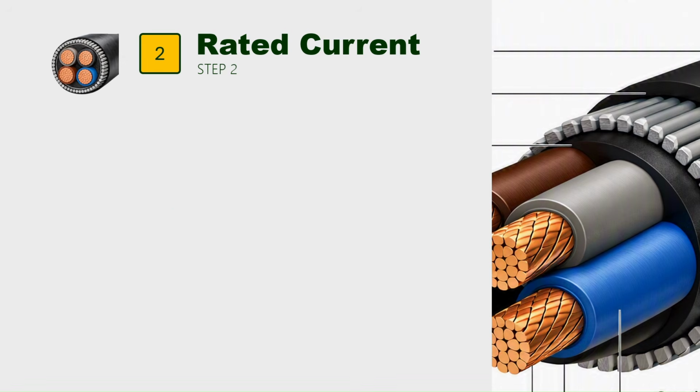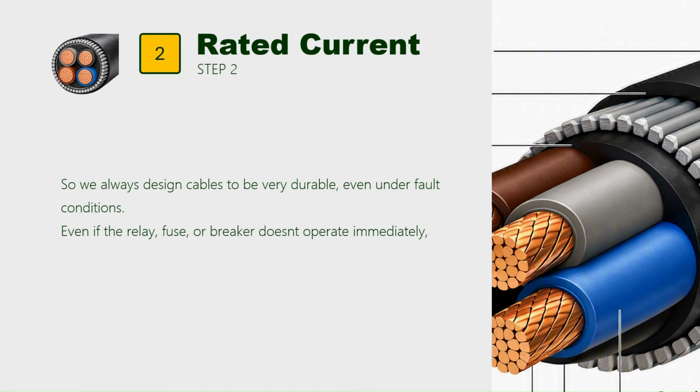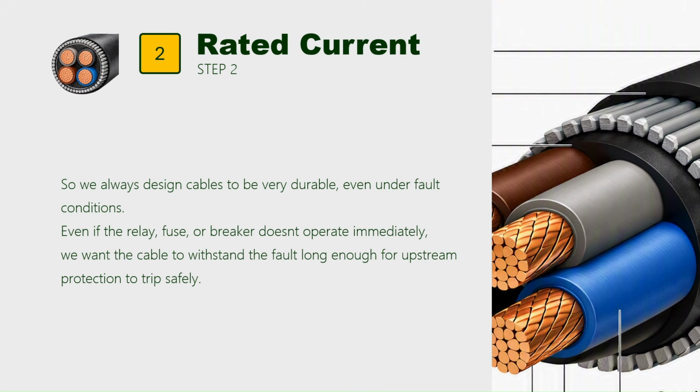So we always design cables to be very durable, even under fault conditions. Even if the relay, fuse, or breaker doesn't operate immediately, we want the cable to withstand the fault long enough for upstream protection to trip safely.